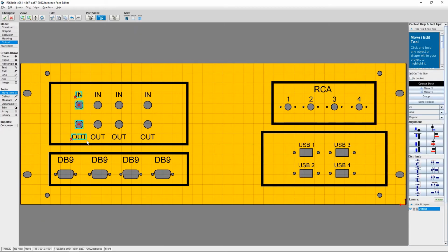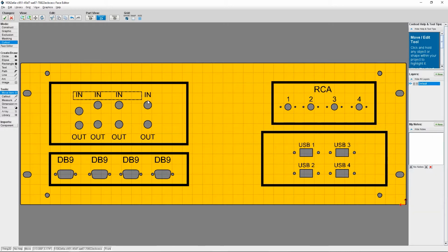The first button is called Distribute Origins Vertically. This one shifts the cutouts vertically so that there is equal space between objects according to their origins. The origins are the red dot on every object. And because we're looking at things from a vertical perspective, Protocase Designer will look at the two objects on the outermost boundary vertically, so the one that's the highest and the one that's the lowest, and move the objects in the middle to be evenly distributed between them.